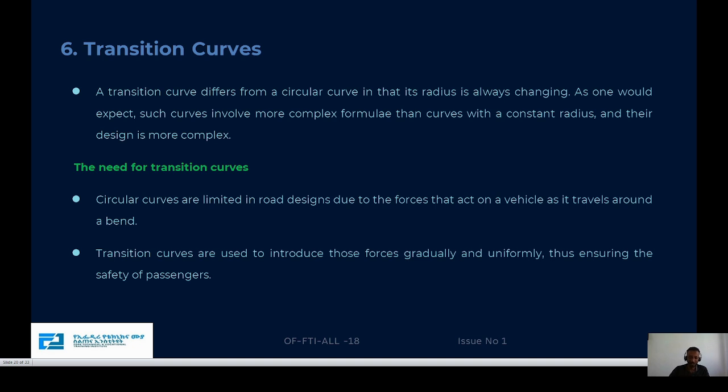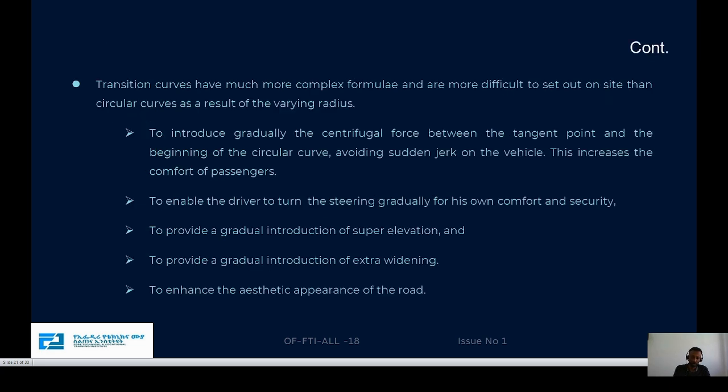It introduces those forces gradually and uniformly when entering the curve. With a circular curve without a transition, the driver travels on the tangent and directly enters the curve. With a transition curve, the driver goes from the tangent to the transition curve and then into the curve. This is gradual and smooth, so it increases safety.